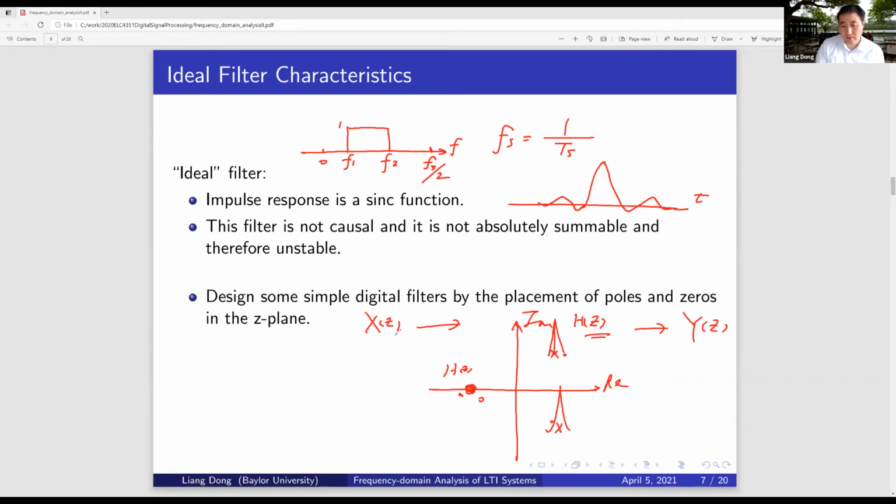So that's indeed what we are doing in filtering. Now this is the Z domain, right? In the transformation domain, it is a product. So we are doing a filtering. We let some components pass, we let other components be removed. Now the Fourier transform is a special case of the Z transform. Simply, we are looking at the unit circle.